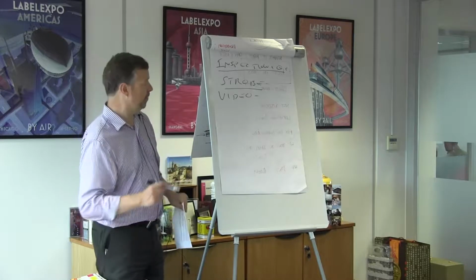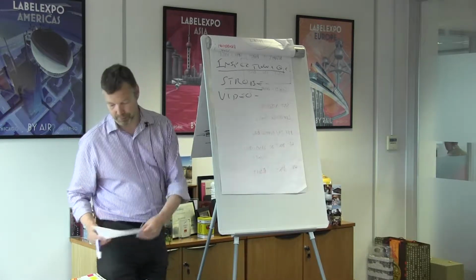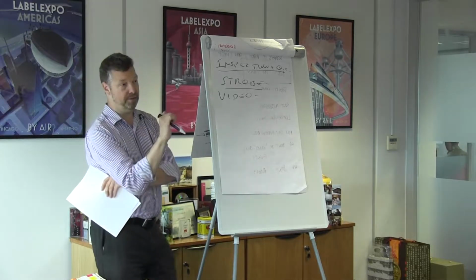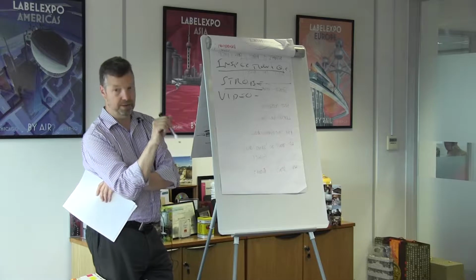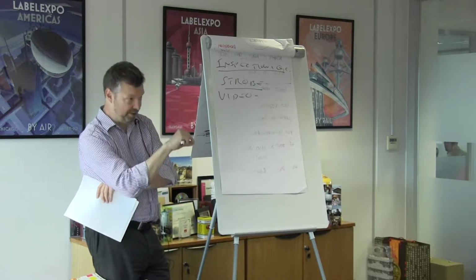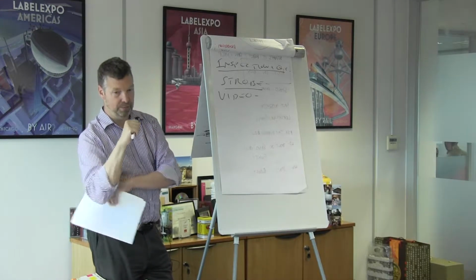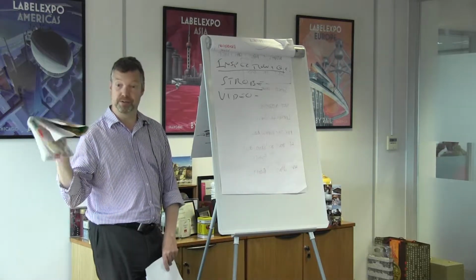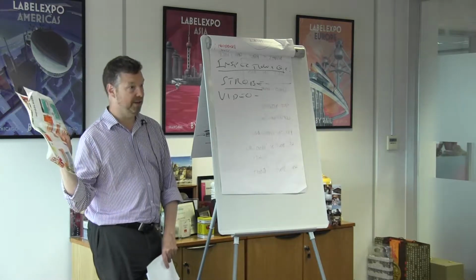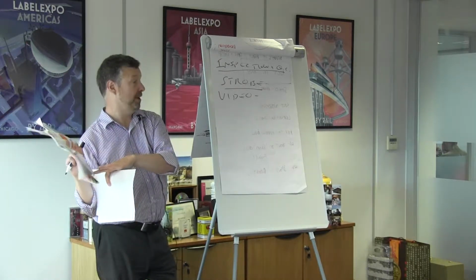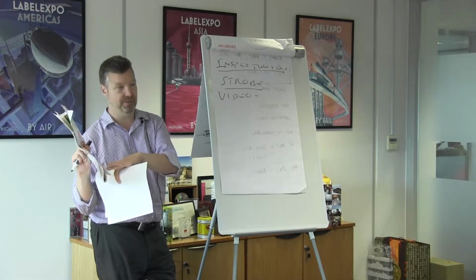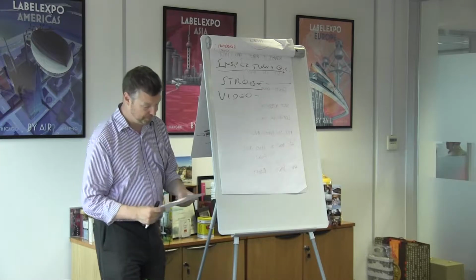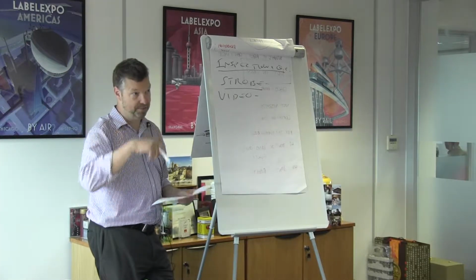Okay, the other problem with the golden image system is it's not very good at checking for variable data. So let's say that you have a pharma label, and every label now has to have a unique serial number on the label. Because it's only taking one photograph of the first lot of images, it's not very good at detecting that the next label is going to be 1, 2, 3, 4, 5, 6, and then 1, 2, 3, 4, 5, 7, and 1, 2, 3, 4, 5, 8. It can't check variable information. That's where the OCR comes in.